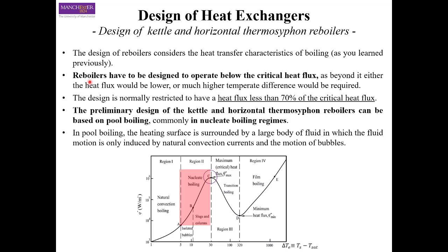Just to remind you what critical heat flux is, in case you forget. Critical heat flux describes the thermal limit of a phenomenon where a phase change occurs during heating, such as bubbles forming on a metal surface that you are using for heating water, which suddenly decreases the efficiency of heat transfer, thus causing a localized overheating of the surface. That can cause either a burnout or surface melting.